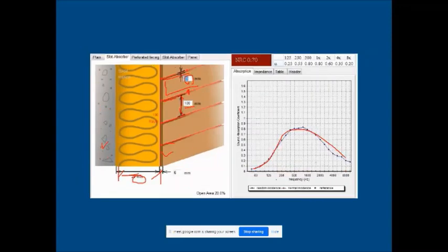Now this will cater maybe from 150 Hz to 4000 Hz as a sound absorber, almost 0.8, right? So when we provide a slat absorber by providing some gap, we can change the gap and you can see the various properties of that material. So this software is very nice, and this is glass. So this is the behavior of sound absorbing properties. For higher frequency and middle frequency, this is performing better when we provide this kind of assemblage.